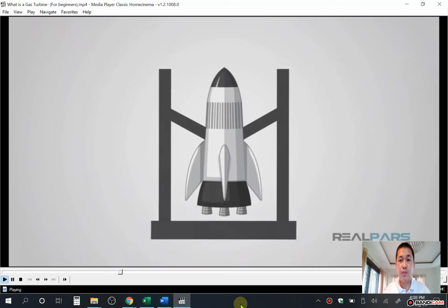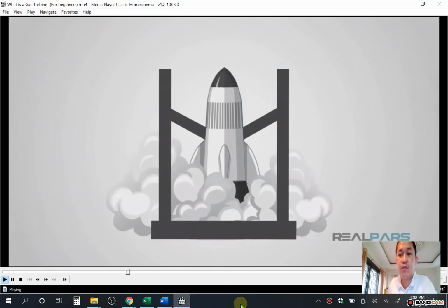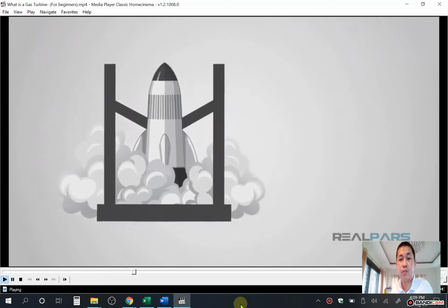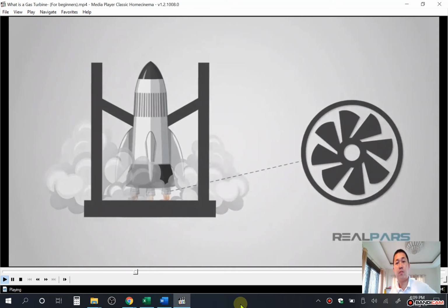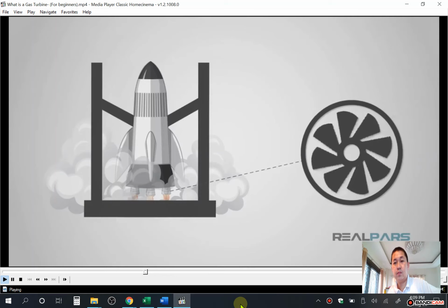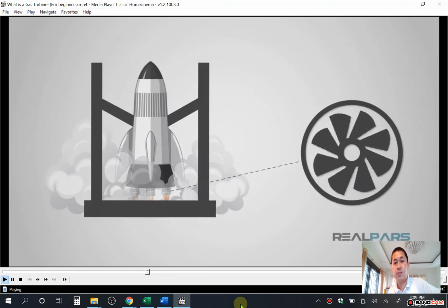And now, suppose I fixed the rocket body with a robust mechanical structure to prevent its movement. What will happen? The high-pressure exhaust gas should be released, and it will have no way but backward. Now, keep this structure in mind, and imagine I put a set of turbine blades in the path of this high-pressure backfired exhaust. You see that the release of mechanical energy, which is mostly in a linear backward direction, will mostly transform into a kind of rotational movement of the turbine shaft.